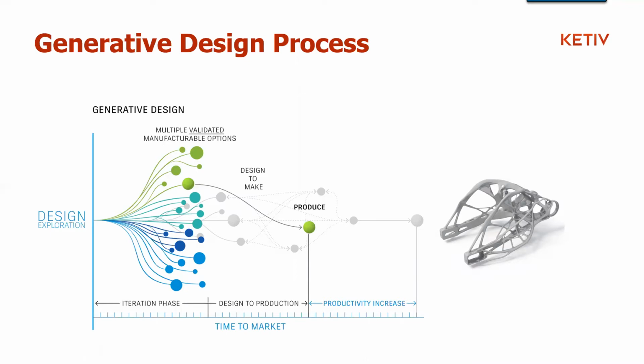And then obviously you don't want to just be stuck with a design and not be able to modify it or use it at the end of the cycle here. So at the end of generative design, you do get an editable CAD model that you can modify. You can rerun generative design if you want. If you want to even decrease the mass or the weight and lightweight it, you can go into NetFab and start some latticing in there as well. So many different things that you can do, but the point is that you do get CAD geometry that you can export out to your CAD software.